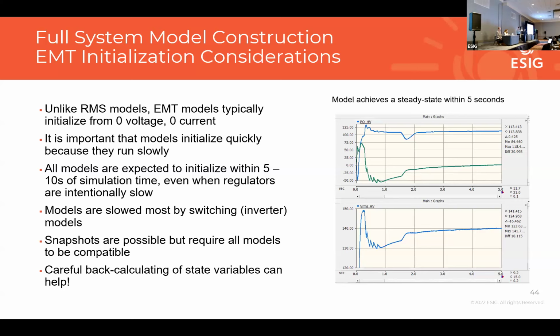One note in terms of initialization, which we mentioned a few times: unlike RMS simulations, EMT models typically initialize from 0 voltage and 0 current, so they have to ramp up within some time frame. Usually we say we want these models to give us a flat line within 5 to 10 seconds. And it's important that they initialize quickly because these models take so long to run.